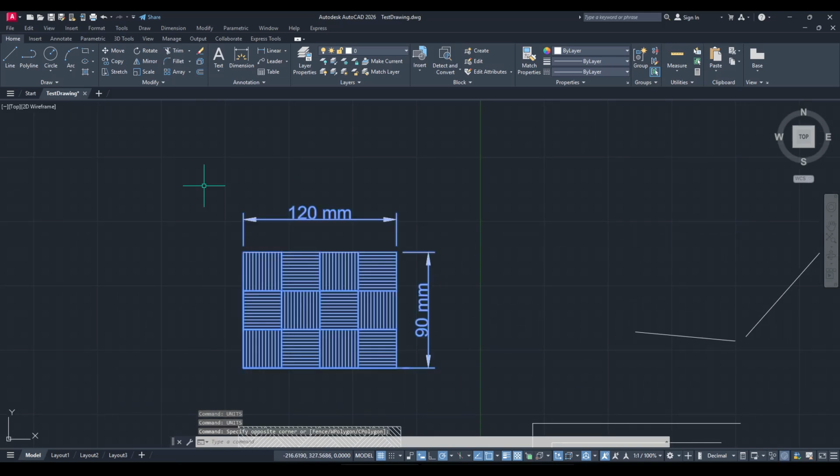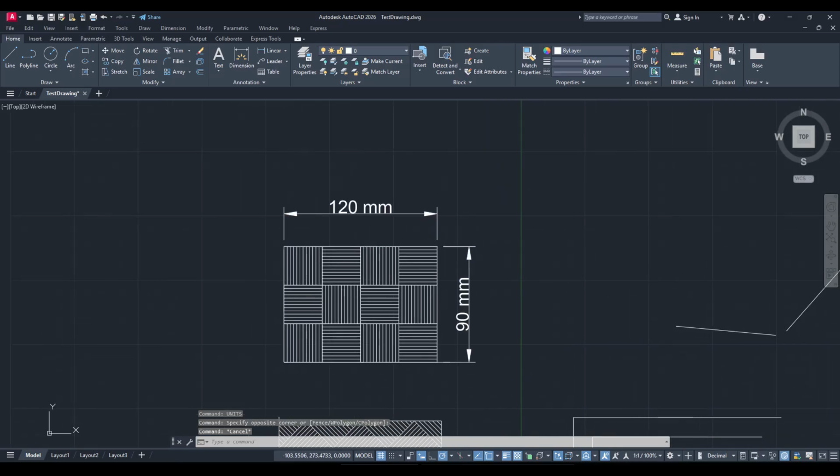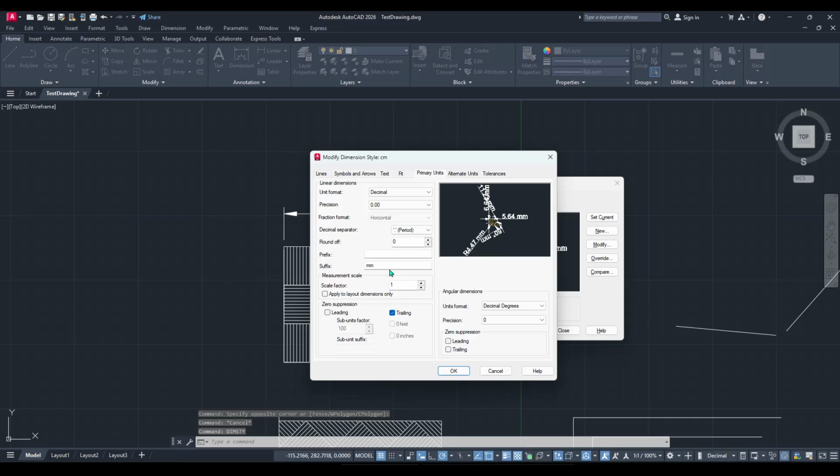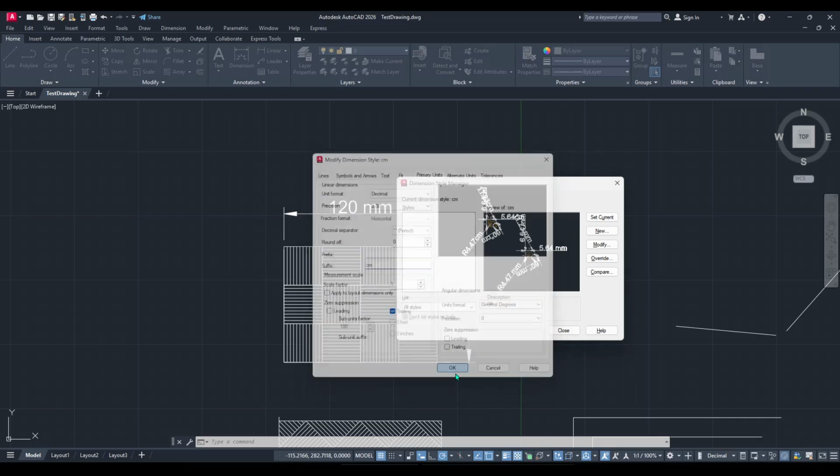A helpful approach is to identify a known real-world distance in your drawing. Compare it to what AutoCAD reports, and apply a single, consistent scale factor across your model. Keep an eye on annotation objects, blocks, and hatches to ensure they stay proportional after scaling. As a best practice, save a backup before you make broad changes, so you can roll back if needed.